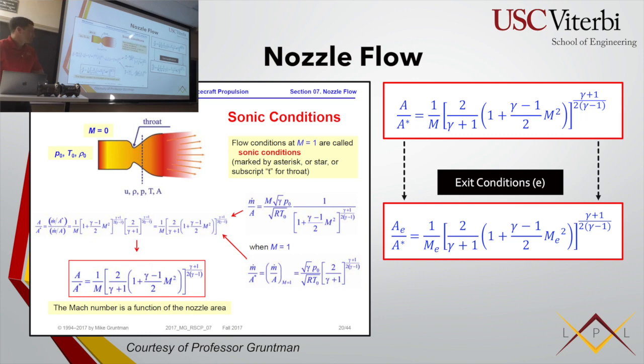And so what that means is if you want a certain exhaust velocity, right, your U_E, it's a function of your area. And so the larger the area, the more velocity is flowing out. I guess it'll make more sense when you go through the equations coming up, but essentially just know that. And this cannot be solved by hand, it has to be done numerically. Like you cannot solve for it if you know a certain area ratio.